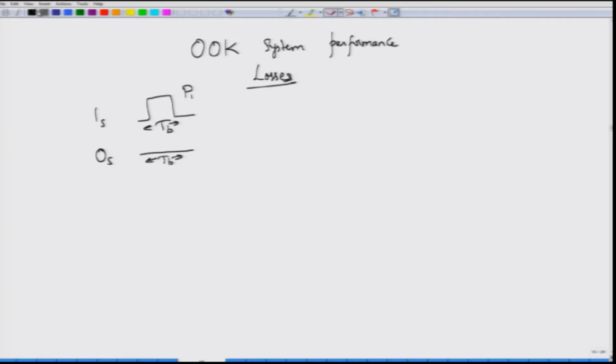Okay. The transmitter side system consists of a laser which is producing your continuous waveform. So, you have a laser here which is having a carrier frequency of omega s. This can be pulse shaped using one of the pulse shaping components that we discussed, such as a Mach Zehnder modulator, and then you have an amplitude modulator that you can use in order to turn on and turn off the pulse shaping circuit. Okay.